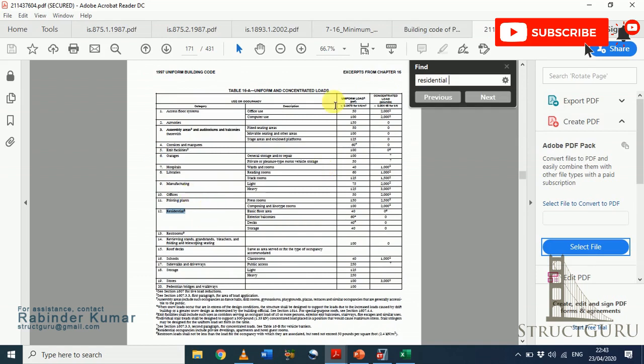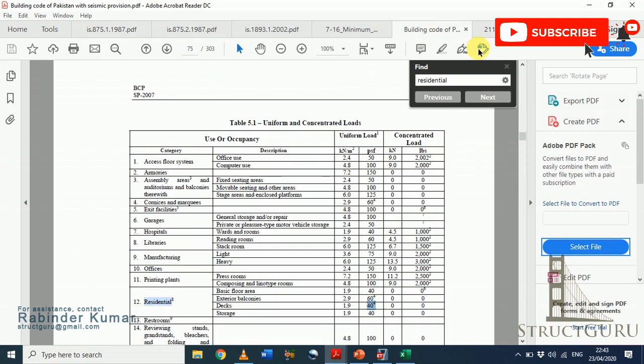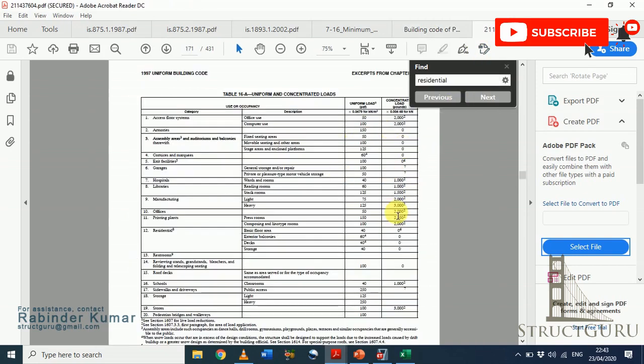So if you refer to UBC code or Pakistan code, the values are almost identical. As you can see, for residential area, it is given 40, 60, 60. Only the table is reproduced in other format. Otherwise, the load values are the same. That's why I told you earlier the provisions of building code of Pakistan are compatible with Uniform Building Code 1997.